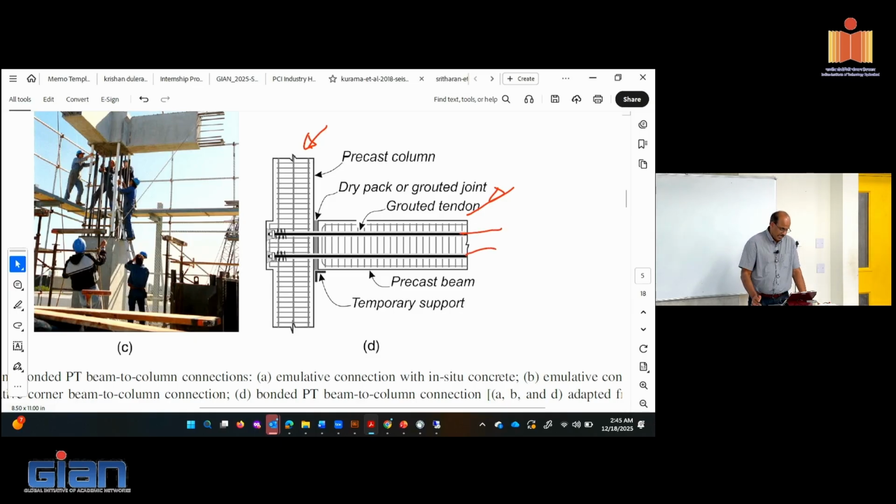They put in the post tensioning. Anytime you apply significant post tensioning, by friction you should be able to provide resistance, because the amount of post tensioning we put in for these systems is pretty substantial.